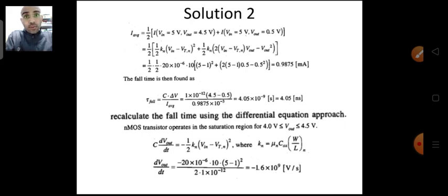We are taking two values at those particular instants, the point where the voltage is at the 90% value, and the other point at which the voltage is at 10% of the steady state value, and then we take the average. We don't consider the intermediate values between the transitions, so that is why it gives you approximate results.